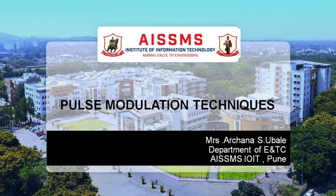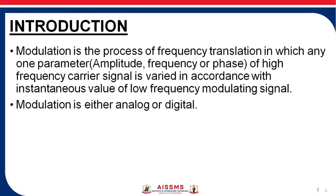Here we are going to discuss pulse modulation techniques. So firstly we are going to see what is meant by the modulation process. Modulation is the process of frequency translation in which any one of the parameters like amplitude, frequency or phase of a high frequency carrier signal is varied in accordance with the instantaneous value of a low frequency modulating signal.